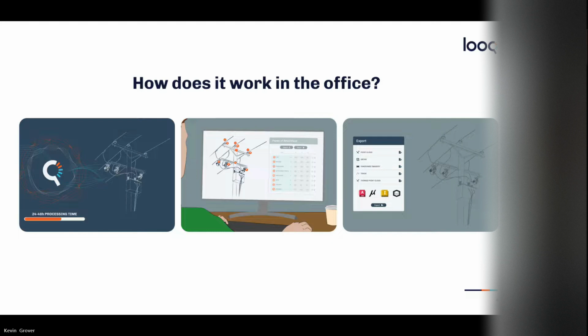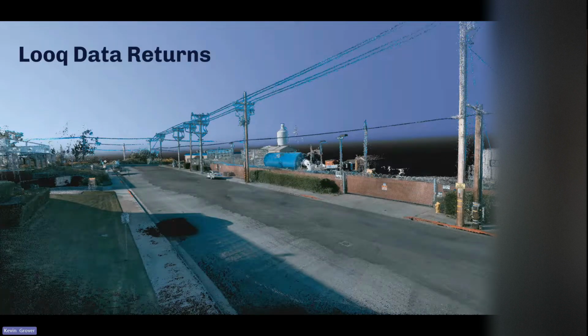In the end, what we're able to generate is something that's going to look like this. It's a three-dimensional point cloud that is very precise, so we're able to take precise measurements for heights and pole to pole measurements. We're also able to do more absolute measurements because we are GNSS based, so the data set is linked to a coordinate system. You can fit it to ground control, so we can start generating more survey grade products from the data set. But this is really what we're expecting out of the quality of data in the end, and this is just from a simple walking capture at the ground level.